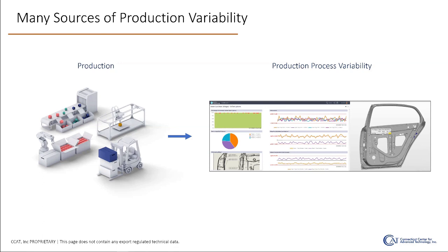In this instance, with power, we were able to see a percentage increase as the tool wore. But in other operations, for example a drilling operation, it's very highly dependent on the material, and on the size of the motor that's turning that tool through the material. If you have a larger motor, you see less of a percentage difference between the signal change when you're cutting with a sharp tool and with a dull tool. So you can't just rely on one signal. And as Dr. Imani had pointed out before, in some of his studies, the power signal actually contributes almost nothing to the overall analysis.